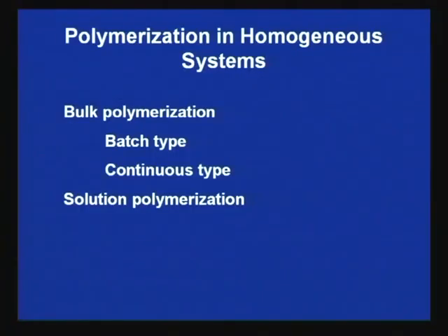So, addition chain polymerization is difficult to manage in industrial polymerization. That is why people go for tubular reactors. There are various designs of reactor. Say people use a tubular reactor, a narrow tube in the form of a spiral, that is a polymerization reactor. From one end of the tube monomers are introduced, and from the other end polymers are collected.